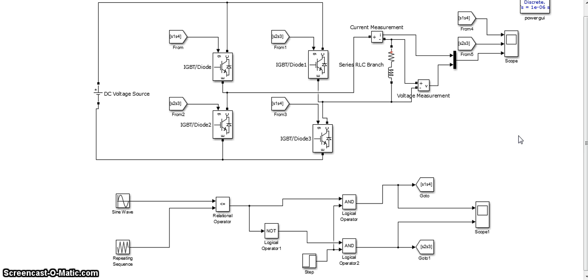using IGBTs. The output voltage waveform of an ideal inverter should be sinusoidal, but practical inverters have non-sinusoidal waveforms which contain certain harmonics. The output frequency of an inverter is determined by the rate at which the semiconductor devices are switched on and off by the inverter control circuitry, and consequently an adjustable frequency AC output is readily provided. The harmonics content of an output voltage can be minimized or reduced significantly by switching techniques of variable high-speed power semiconductor devices. The DC power input to the inverter may be battery, fuel cell, solar cell or other DC source.